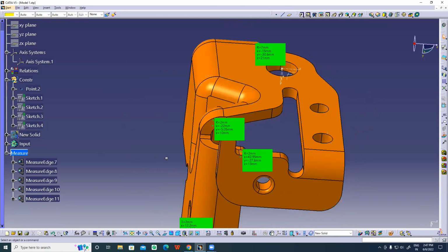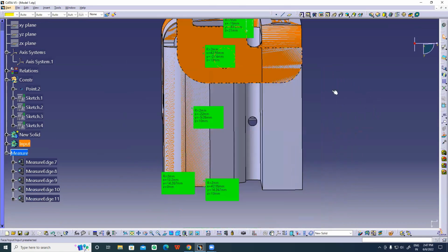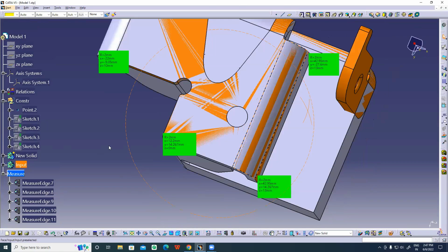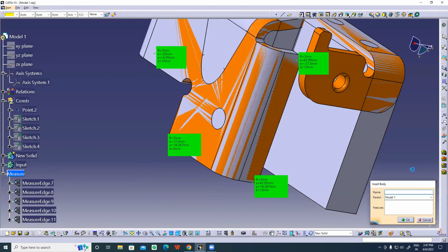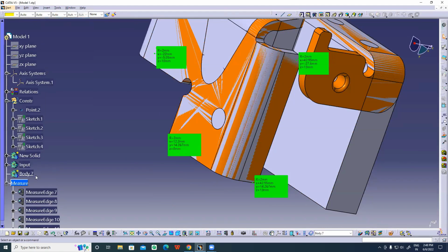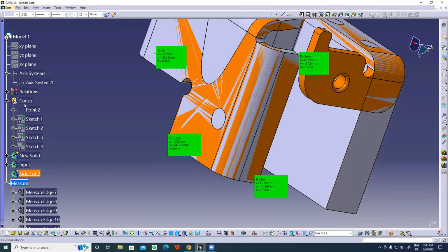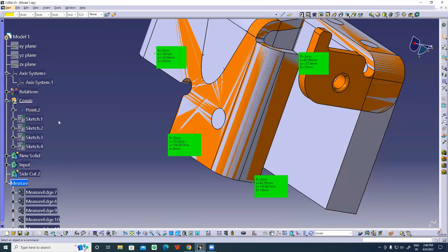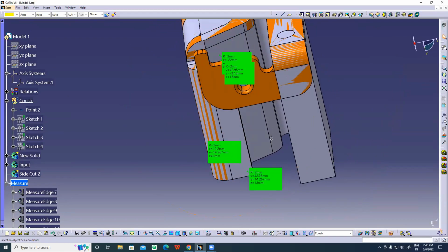Okay, before doing that, first thing is in the input solid, you can see this portion is coming. In this place, I don't want any body to be available. So I wanted to remove it. Okay, I'll be inserting a new body. I'll be naming the new body as side cut 2. First, I need to create a sketch. I'll be defining a construction work object, and I wanted to create a sketch like in this view.